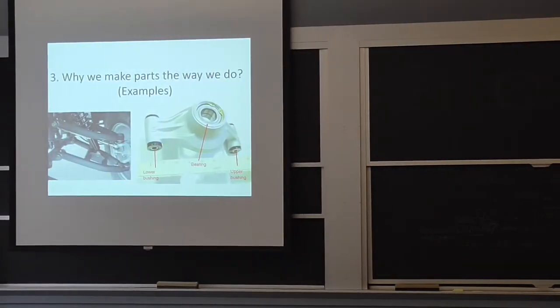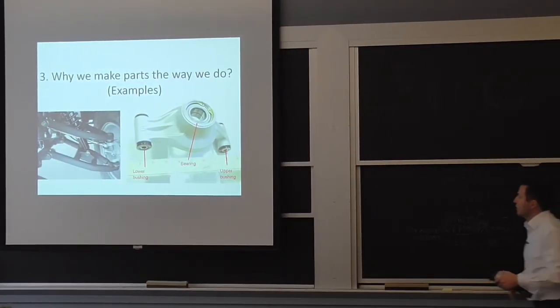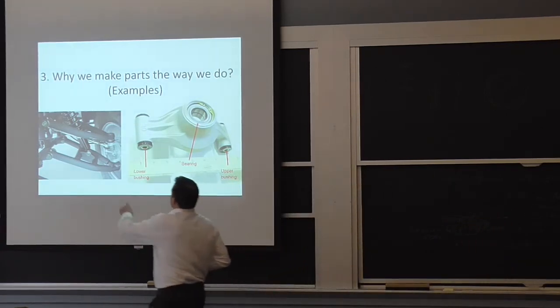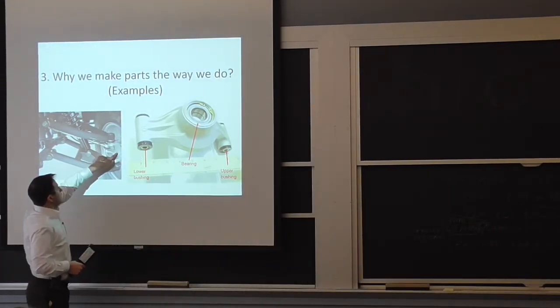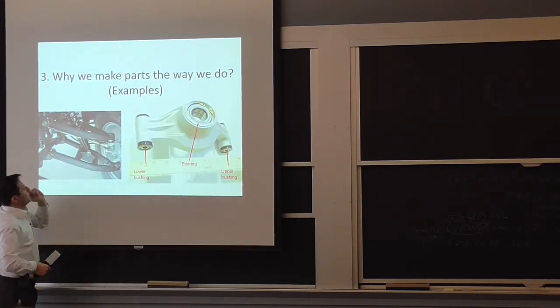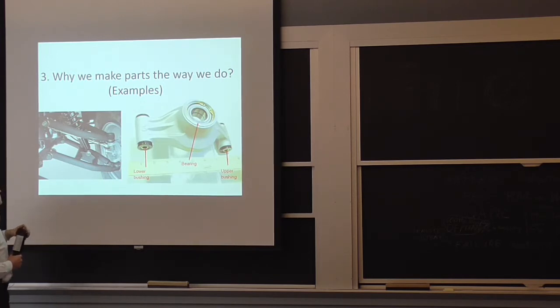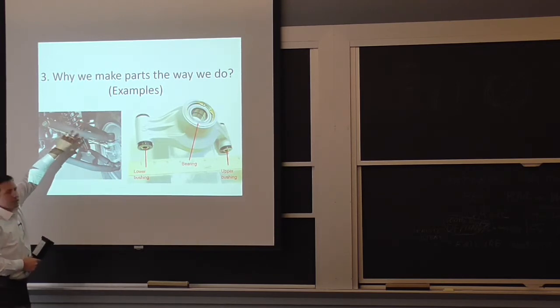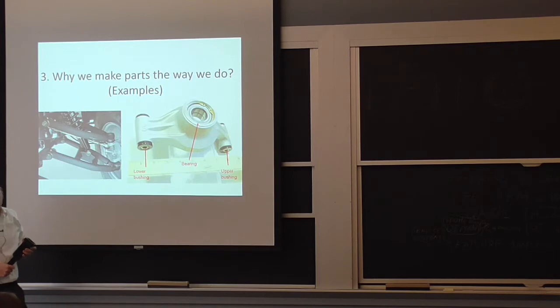What's in black, you've got two A-frames that are under suspension to the main frame. So the piece you're looking at is this one here. It's got the bearing for the wheel. We put the hub there, and then you have attachment top and bottom. It's for a rear wheel as opposed to a front wheel, and everything here is just the suspension going up and down.